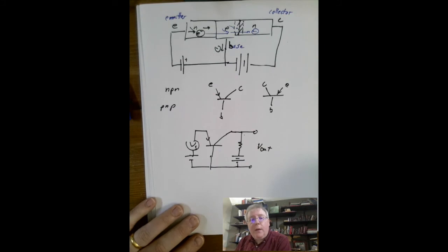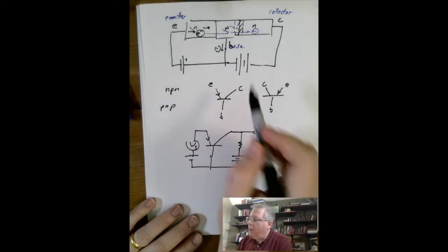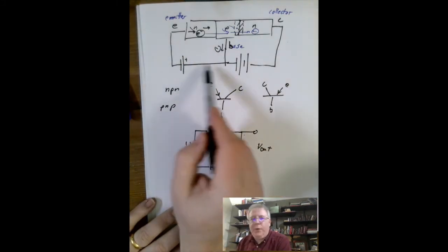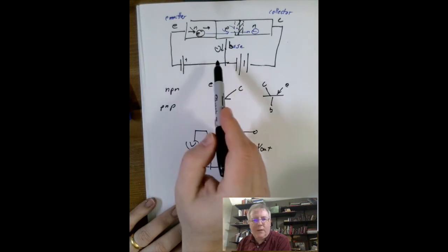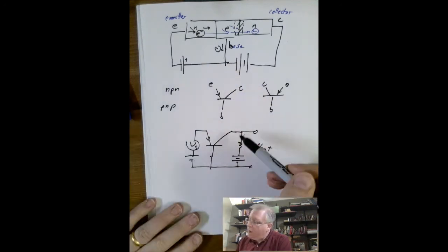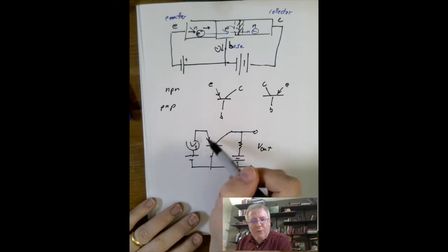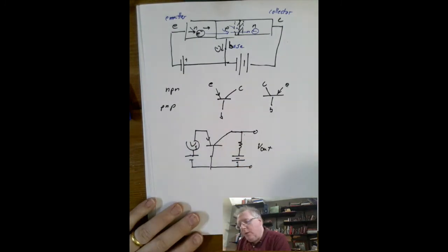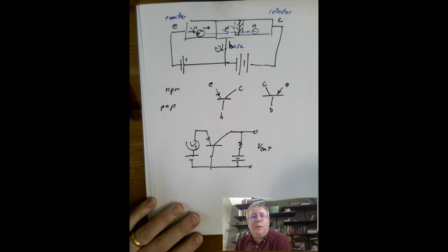So now we finally have the ingredients for an amplifier. You'll notice that this will only work in one direction. If I reverse bias this, then it won't run at all. So this amplifier would only work with positive going signals over here. The solution to this is you run two transistors, something called a push-pull amplifier, which requires at least two transistors.